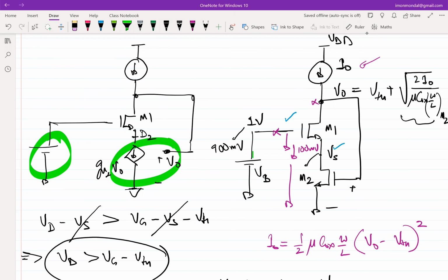Which essentially means that when the gate moves, the source has to move. And this is again the same thing that happens if you bias with constant current, right? So is the gain 1 or less than 1? Ideally, we have still not put any non-ideal elements here, right? Okay, fine. As long as you are satisfied with this, we are now in a position to figure out what can get affected at the lower limit of VB, right? So now I am reducing VB to figure out what the lower limit is. What is likely to get affected?